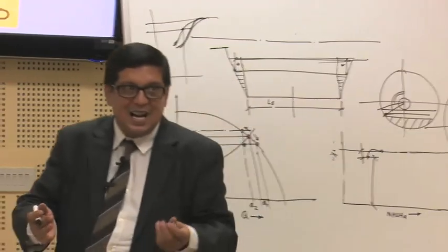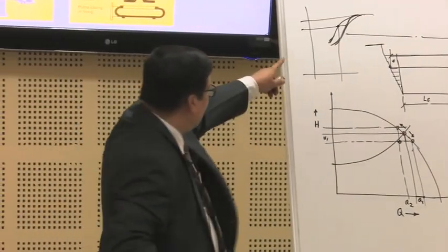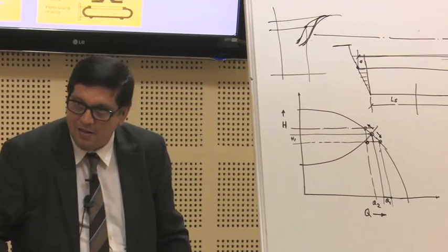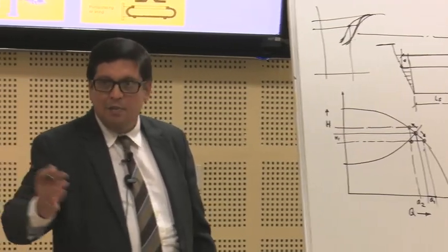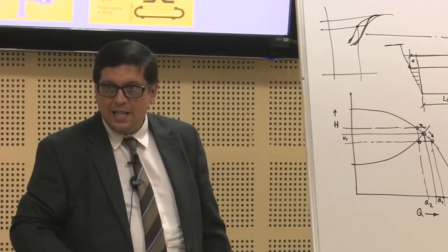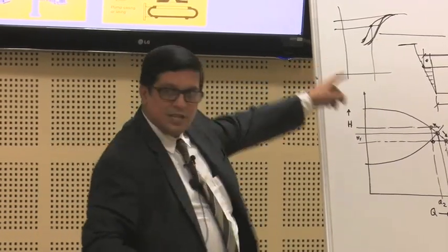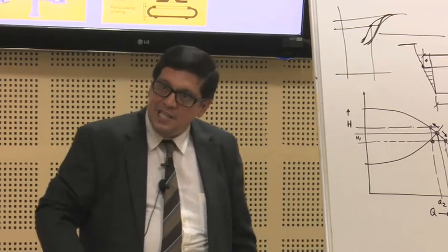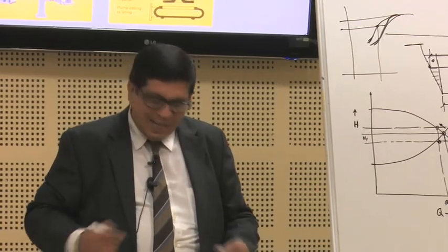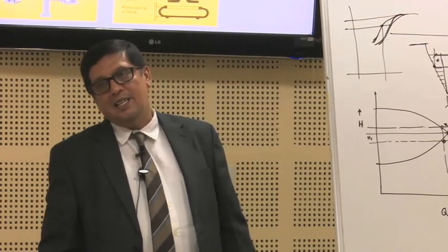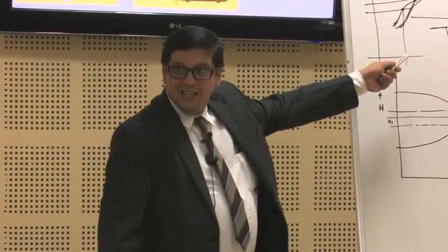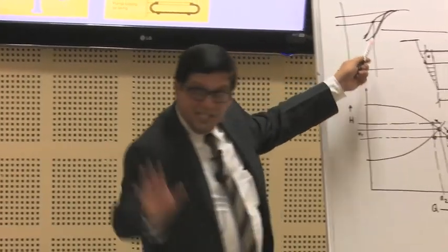They have shown us a cyclone overflow of this nature, which cannot happen. I said the sampling was wrong. He said no, sampling was not wrong. Then he took the logbook and at least 5 or 6 samples more or less showed a similar trend. Then suddenly it appeared to me, how is the pump behaving? Then they said the pump is having a problem. I said, is it hunting? He said yes. So it is that.